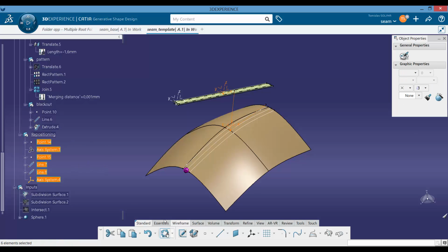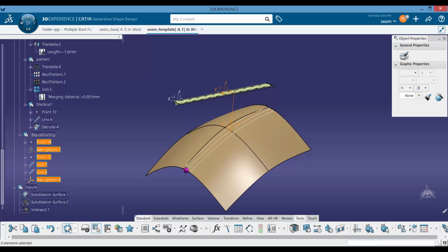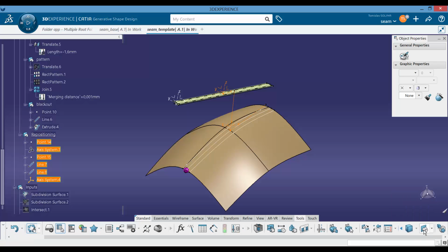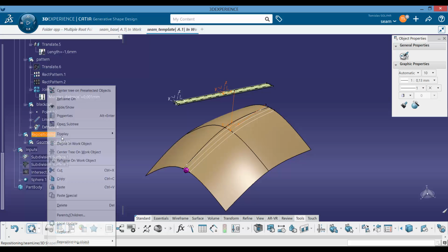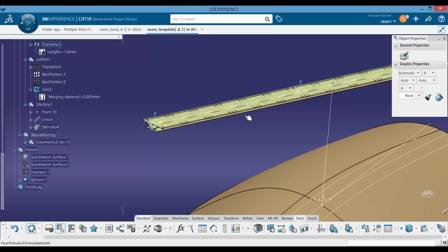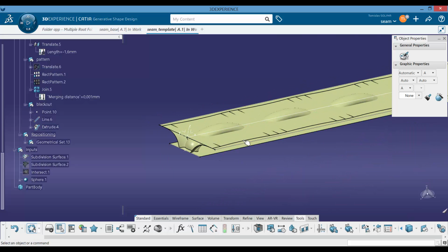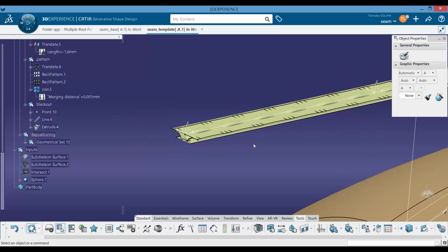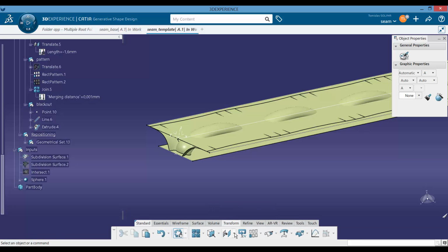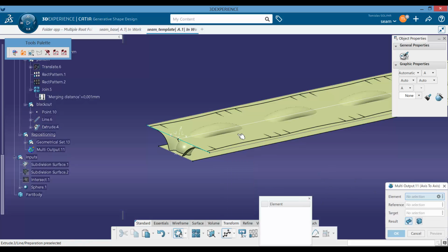Before we do this, let's simply pack this in additional set so that it doesn't disturb us later when we don't need it. So we'll add additional geometrical set. We will not even name it. And now we can grab all this geometry that we want to have, that we want to use down there. We will transfer it axis to axis. So we will need transform, translate, axis to axis. Element won't be one, it will be all this set.